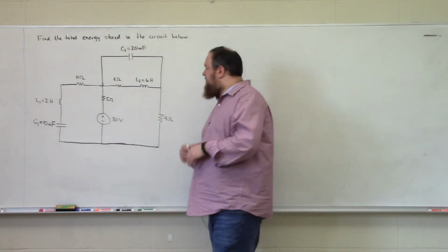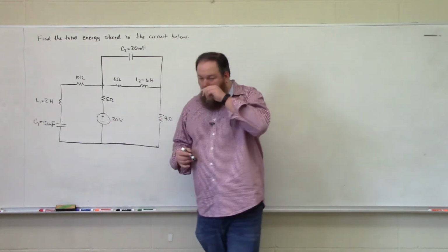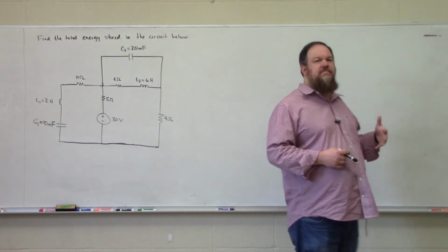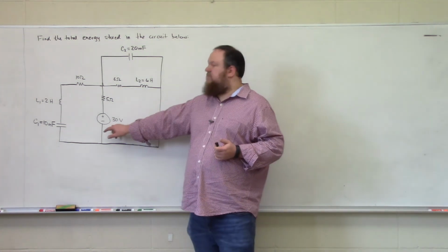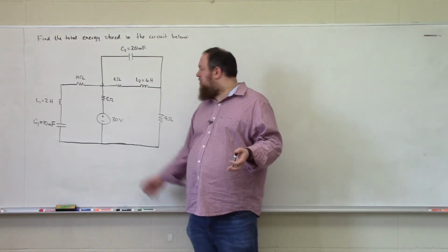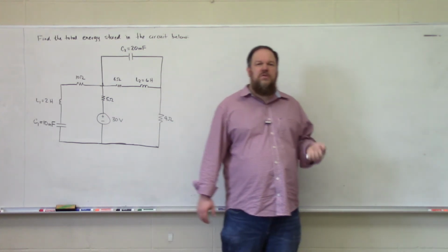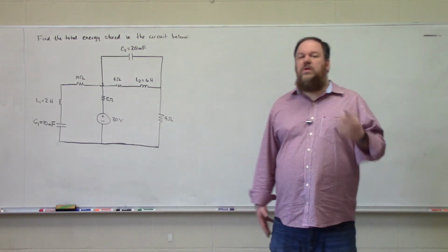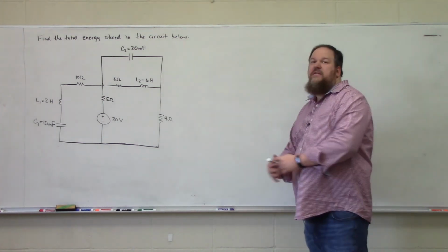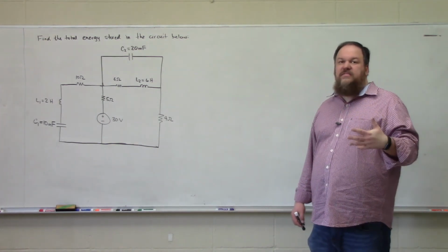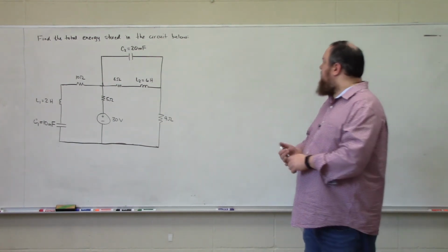And I can see this because I only have a single source in the circuit, and it is a DC source. So what does the concept of DC steady state mean? Well, if my excitation is a DC term, like this voltage source, then that means that all of my voltages and all of my currents in my circuit will also be DC or constant quantities. Now this is a very important concept with regards to circuits containing inductors and capacitors.